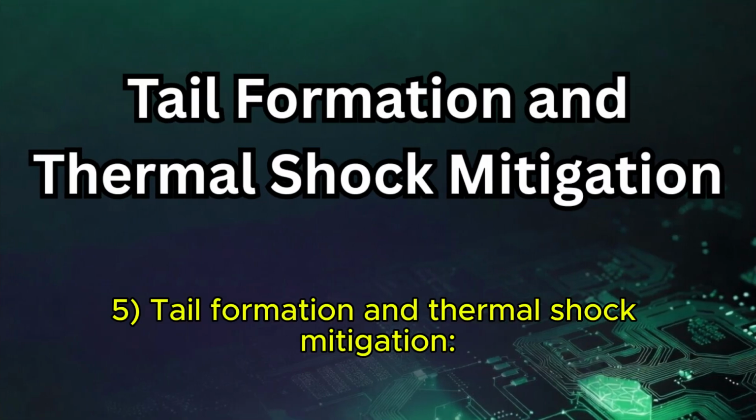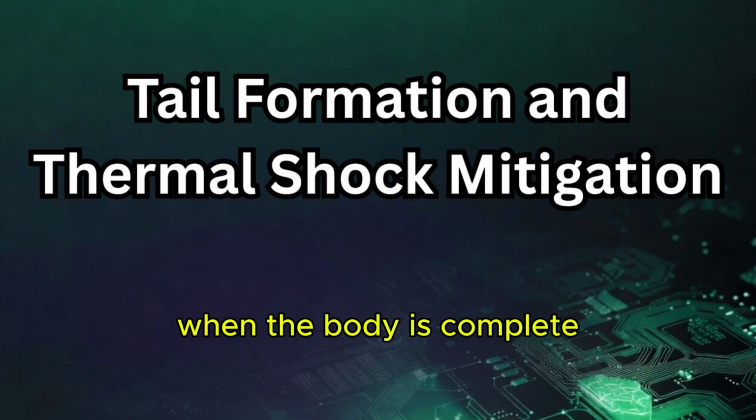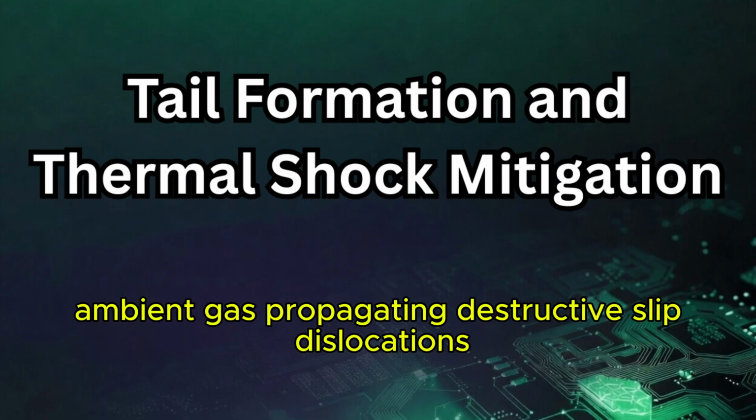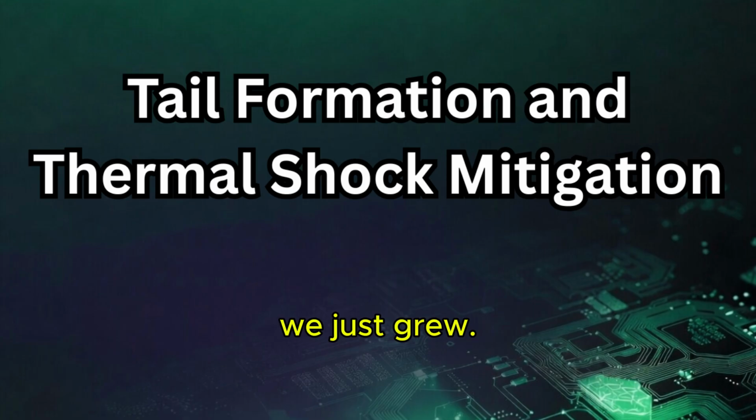5. Tail formation and thermal shock mitigation. We cannot simply yank the finished crystal ingot out of the melt when the body is complete. Doing so would subject the white-hot solid to a sudden, catastrophic thermal shock as it hit the cooler ambient gas, propagating destructive slip dislocations all the way back up into the pristine body we just grew.